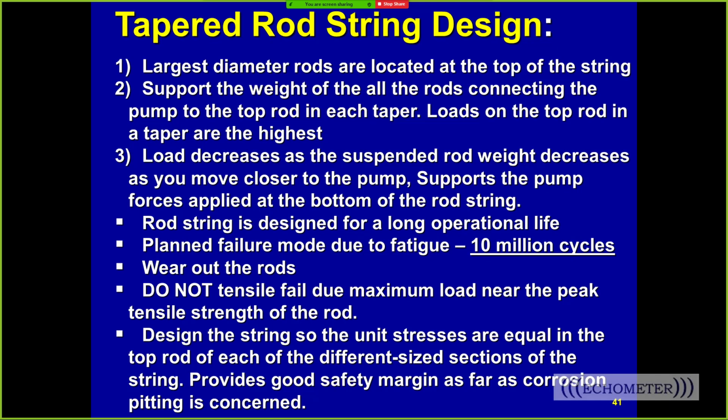But okay, so how are we trying to fix that? So Gustavo and Ken Skinner just went out to a test well near Echometer's office, and we removed the downhole load cell from a well that we're developing with a group called ALRDC. We're developing a downhole load cell to understand how mechanical friction due to dog legs is applied to the rod string. And once we understand that, we'll be able to build a better model that will model that. So right now the models are not very good because nobody has ever really measured it. It's all just theory, and I don't think it's right. So QRod does just as good as anybody. QRod matches the best. So I just say use a true vertical depth and you'll probably be fine.